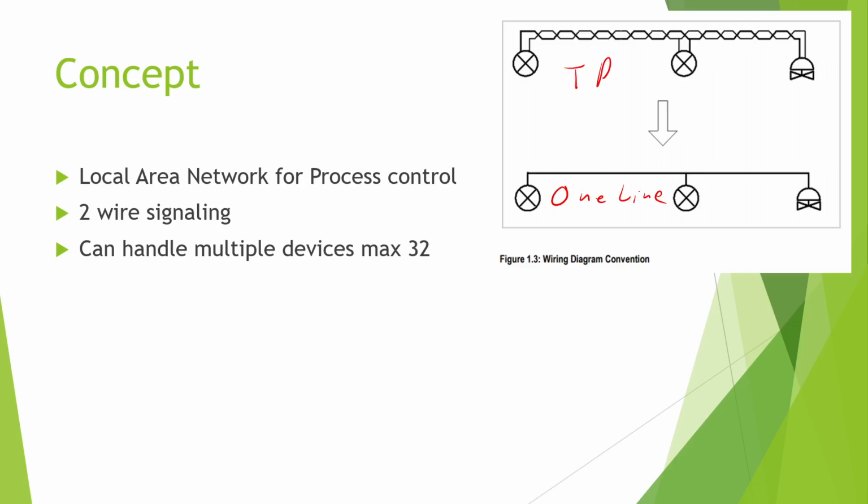And then the last thing is repeaters are allowed. So that will help increase the length. It might also help increase the number of devices that can be put on the bus. So a little bit of give and take in there. Repeaters, you think about again the world of the internet and how we're connecting from here to California. We don't have one wire that goes from here to California without the signal changing in there. Or we're hitting a lot of routers along the way. Even the longer lines with fiber optics also have repeaters on them. So repeaters are a necessity in the world of networking when we start getting the long distances. Like that. All right.